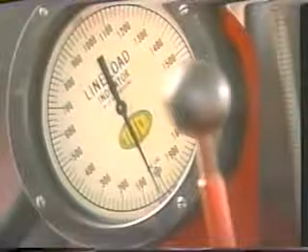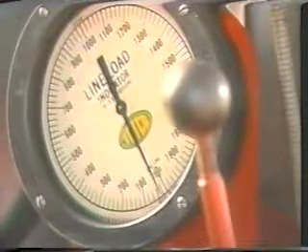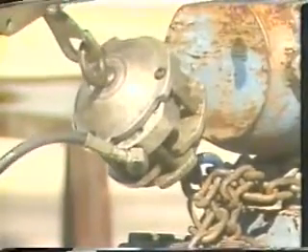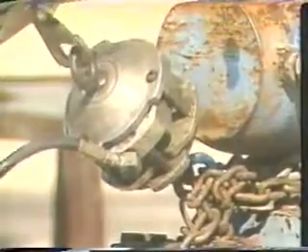As we'll see shortly, this information tells the operator many things about what is happening downhole. The standard device for the industry is the Martin-Decker weight indicator. This weight indicator's primary component is a load cell, which is secured to the wellhead or some other equally secure location as close as possible to the tree.